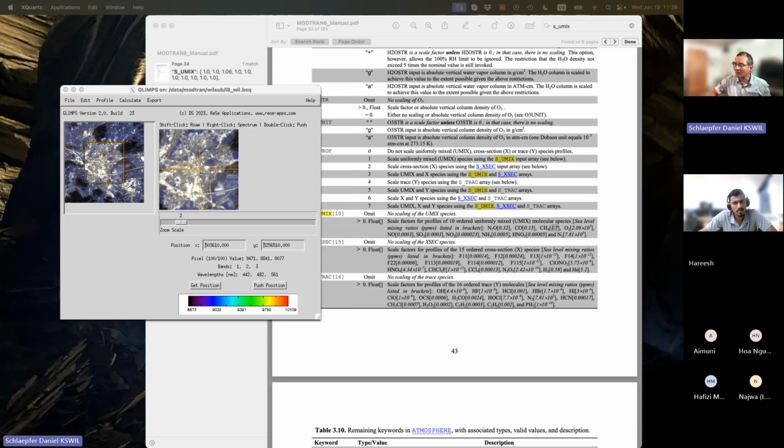TIFF, GeoTIFF and ENVI can be imported here and shown and analyzed. But anything else needs to be imported maybe in ENVI or wherever, if the Sentinel original data are JPEGs and they are coming one band, one file only. So you have to integrate them into one file at first. That's something we do in the AdCore module. So if you do MSI correction, we have this routine which takes all the Sentinel files and puts them together nicely. But that's not something we have in the standard in this package.